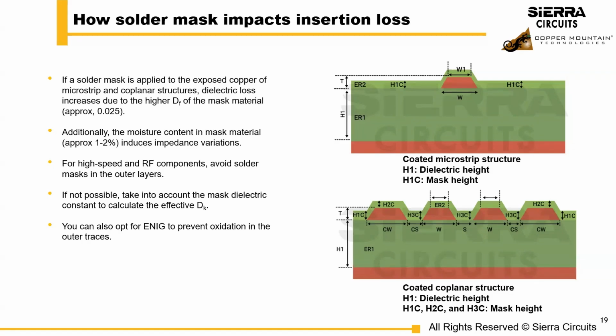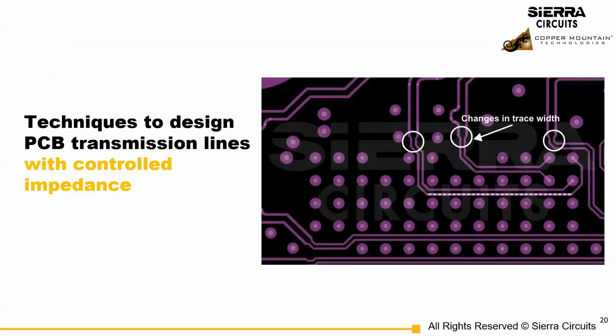And as a separate note, if you put down on your fab drawing a minimum of 1 mil of solder mask, most fabricators that pay attention to the note will put down 2 coats of solder mask to ensure this. So you'll be getting more than 1 mil. So just use that as a reference.